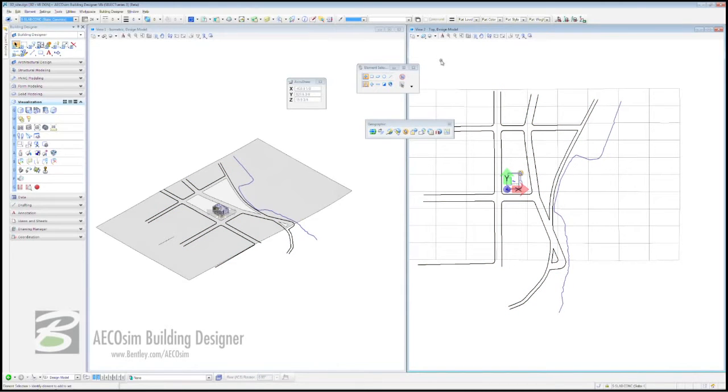What we can do now, though, is go one step further, because now we can take this work and imprint it onto the terrain surface that we pulled in from Google Earth. To do that, we need to come across to Solid Modeling tab in our task-based interface, and first off, we need to come to Solid by Extrusion, because our terrain is only 1 pixel deep, and it'd probably be a lot better if we gave it a bit more muscle.